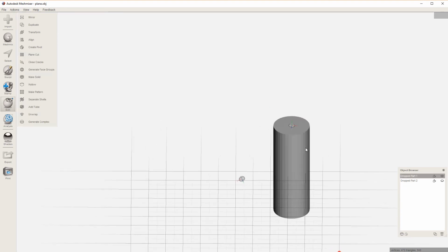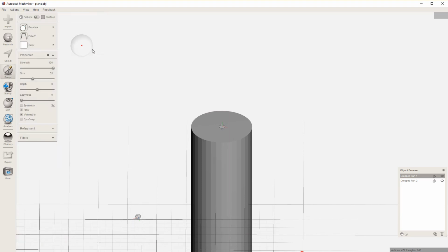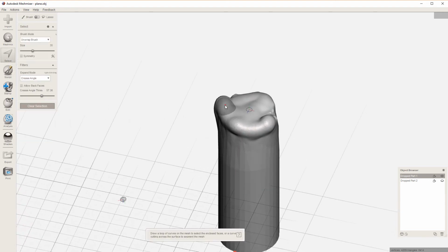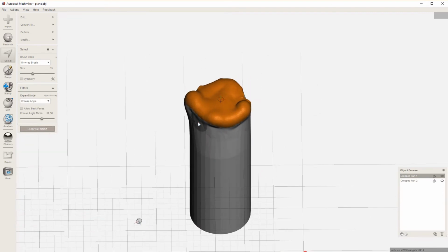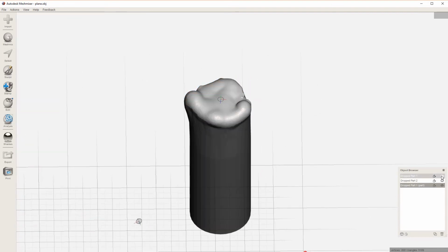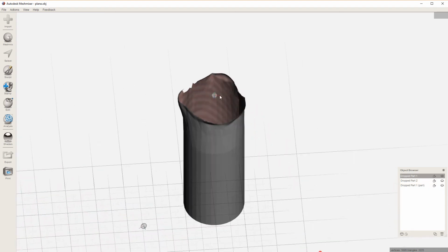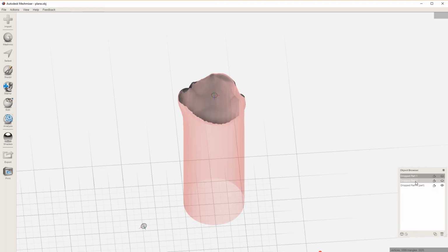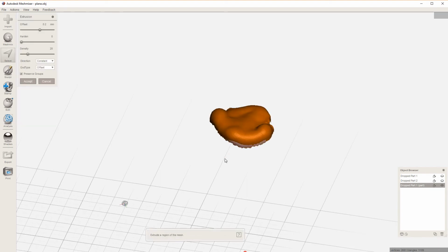One way to do this as well would be, for any surface that you want to copy, some sort of surface like that, you can just select the surface like this, select whatever non-planar surface that you want, and extract it. So you can say Y, and what that will do is essentially cut that out. You can also offset it with a 0 offset if you want to keep your initial object. But now you have this surface. You can select the whole surface.